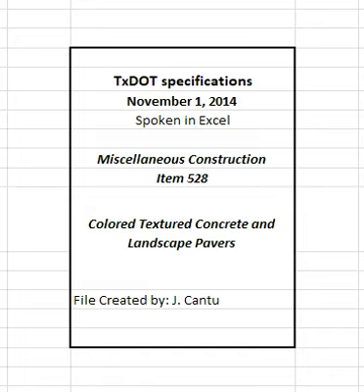2.2.1 Pavers. Furnish pavers meeting the requirements of ASTM C936, made using normal weight aggregates conforming to ASTM C33, and conforming to the shape, color, laying pattern, and dimensions shown on the plans. Furnish certification from the manufacturer stating that the interlocking paving units have been tested and meet all the requirements of ASTM C936. Furnish additional paving units when required for testing by the department.